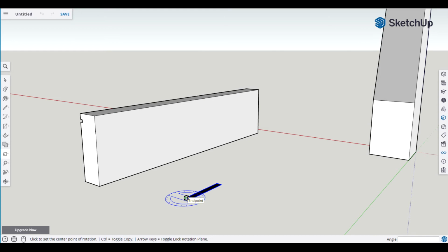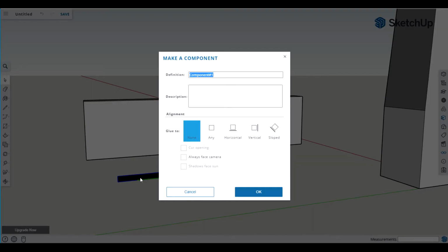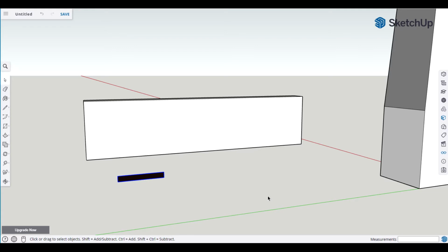and I think we want it on the green, so let me hit the escape key again, and then hit the left arrow key, Q, Q, and let's rotate this down 90 degrees, make sure it's 90, hit the space bar, good, and now we have it in the perfect orientation. Triple click it, make sure it's a component, type in G to get the component screen, and let's type in pocket hole. And we hit enter.